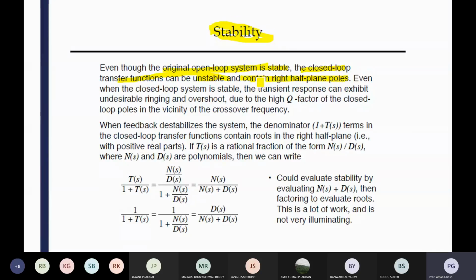So what may cause this? If the switch has some voltage stress, and due to converter dynamics and stability issues, the voltage appearing across the switch comes to twice its standard value, then automatically that switch will be burned out.